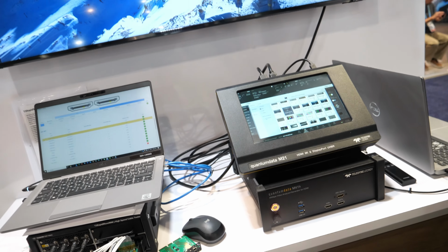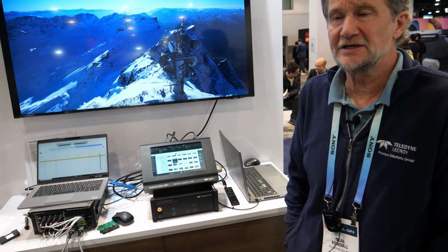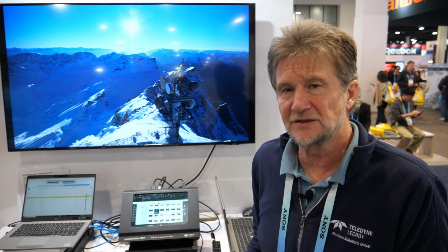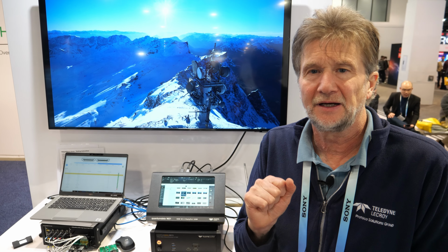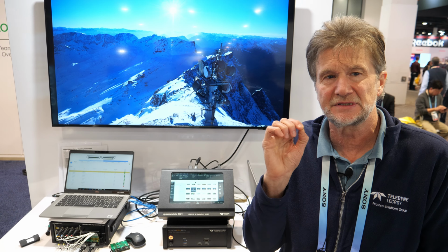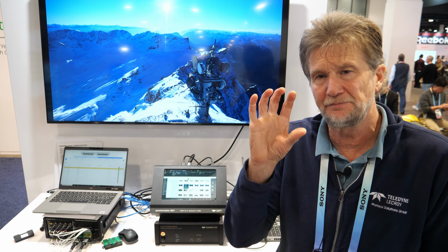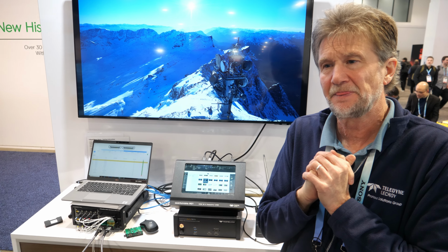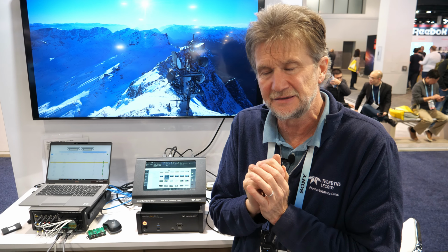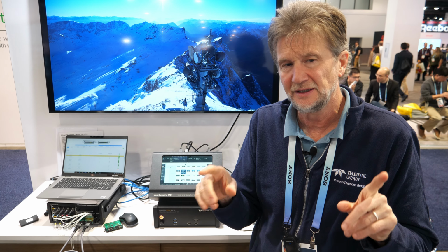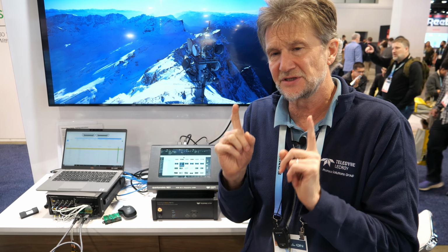And how do you do the signal analysis, what do you call it, deep packet? Okay, so we have a unique solution in that we can look at all the packets going across the main link, whether they be guard bands, preambles, all the metadata, all the packetization in Fixed Rate Link protocol, new with 2.1, the 8K standard. There's also metadata and video and data island information that we can all see. You can see if it's there, you can see if it's in the right place, and you can see if it's populated correctly.